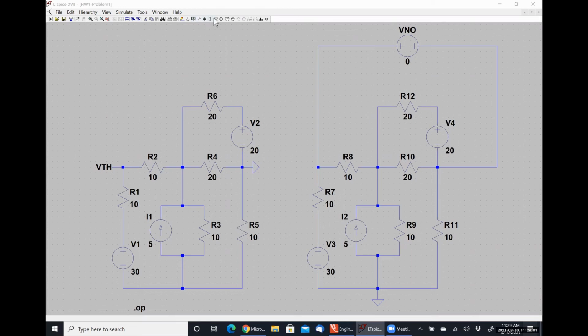Resistors, capacitors, inductors, diodes, and then this guy right here, which looks like a digital logic gate. I don't know how many of you have had 333 at this point, but that's the components button. So that's where you can find literally everything else, from op amps to voltage sources to dependent sources. All that kind of stuff is tied up in here.